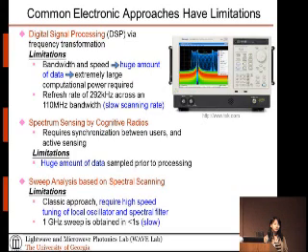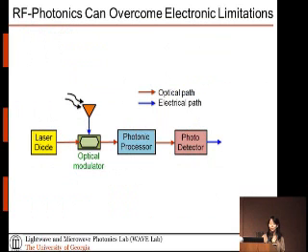And the last approach is pretty classic, which is sweep analysis based on spectral scanning. That's what we have been using in our spectrum analyzers. It requires high-speed tuning of the local oscillator or spectral filter, which governs how fast the bandwidth is scanned. The fastest that people have obtained right now is a 1 gigahertz sweep in 1 second. So for 1 gigahertz of bandwidth, you need 1 second to sweep it. It's still relatively slow. It will just sweep slowly in this way, and you obtain your signal after 1 second.